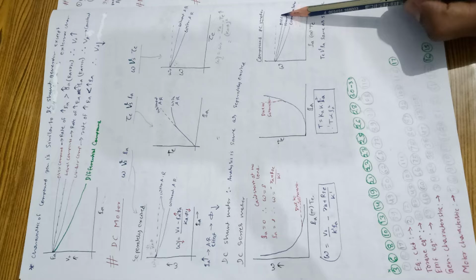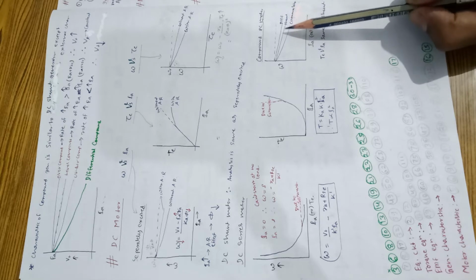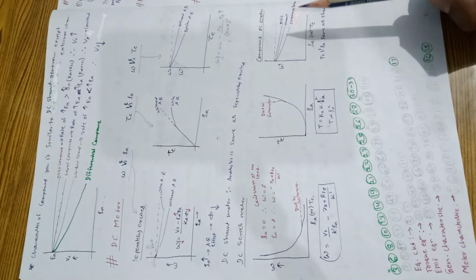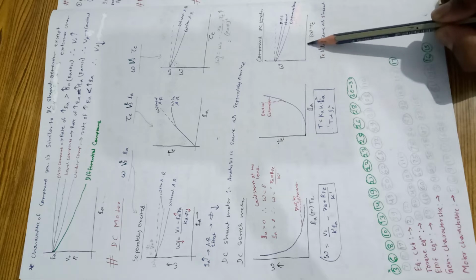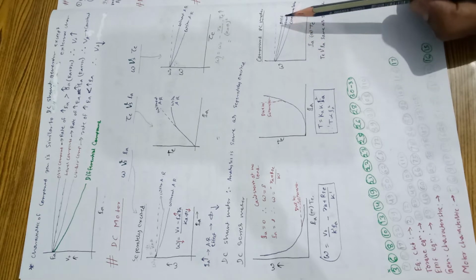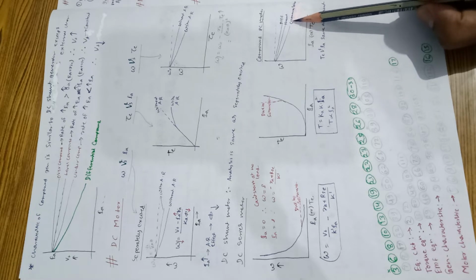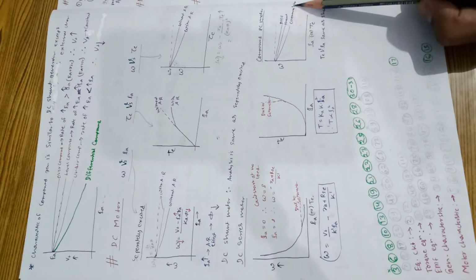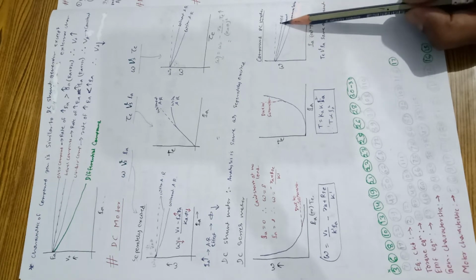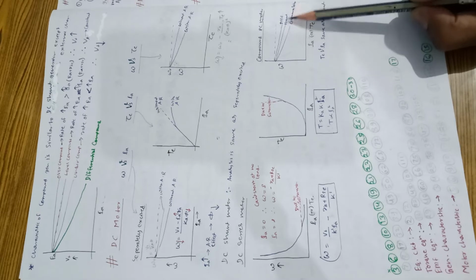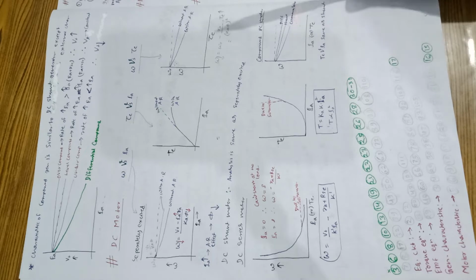After that we have shunt. If the field flux is minimum, it means more speed. Then we have the highest flux in cumulative, so it is at the bottommost part. For the uppermost part we have differential, then shunt, and then cumulative compound. This is the logic behind this.